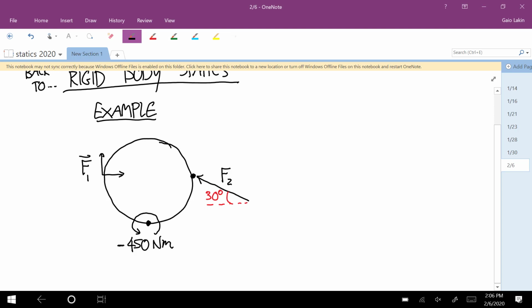But this symbol, people use this a lot for two-dimensional statics and two-dimensional models. That's sort of misleading about what this is, remember. Remember that a moment is always a vector, okay? And so to think about the direction of that vector, you have to use the right-hand rule with that rotation. So if it's going this way, that's a moment in the positive z direction coming out of the board.